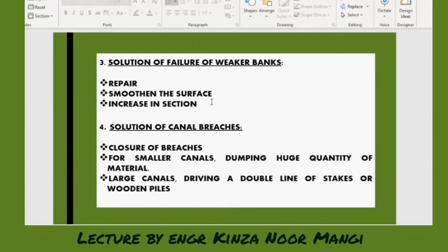what will happen is that they will cause deep hollows at the bottom of the canal or at the side. So it is better to keep those roots, just cut them off instead of digging the whole roots out of the soil during the excavation, because that will again, not sooner but later on, with the flow of the water, allow seepage to occur through those cracks or hollows that are created.